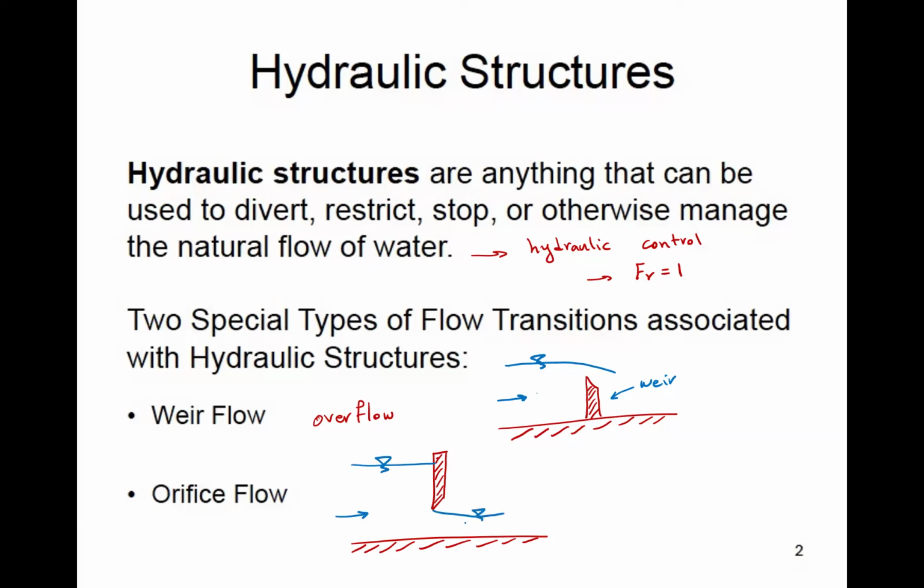So it's more of an underflow type structure. These are called gates or sluice gates or slide gates or different terms, but these are really gates. So in reality, these could be a simple plate, really, depending on obviously scale and dimensions and size and so on, but they're really a vertical thin structure, both weir and sluice gate, and they're basically obstructing the flow.